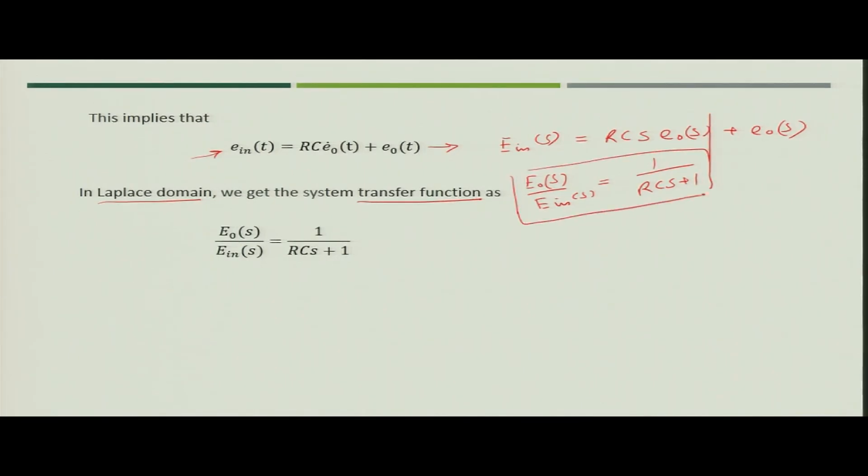So, with the help of the conventional equations related to Kirchhoff voltage law or Kirchhoff current law, you can convert your circuit into the Laplace domain and then find out the transfer function of the system.